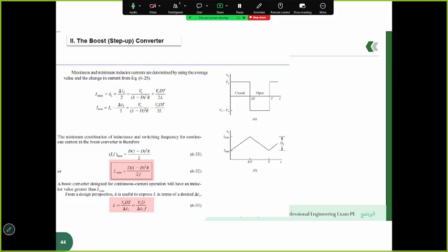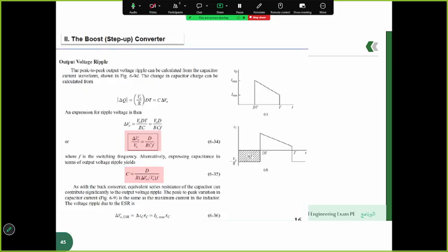The final equations confirm that the average inductor current can be expressed in terms of the input and output voltages and the load resistance. The waveforms visually illustrate the minimum and maximum inductor currents and the triangle shape of the current ripple.